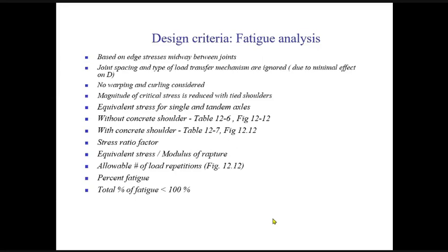There are equivalent stresses calculated for single and tandem axles. That is why we were interested in distributing our traffic in terms of single, tandem, and maybe tridem axles. Those values, the fatigue values and the allowable stresses, have been given in Table 12.6 and Figure 12.12.